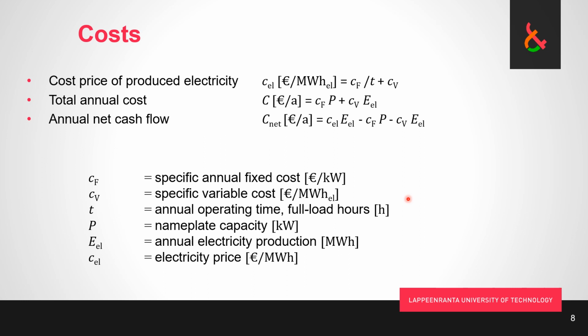So for example, in combined heat and power plants, typically they run a big part of the year at partial load. So we talk about full load hours. So that means how many hours the plant would have to run at full load to produce in a year the amount that it produces. So in reality, a typical cogeneration plant producing district heat, for example, might run for 6,000 or 7,000 hours per year, and 2/3 of it may be at partial load, so that the full load hours is going to be maybe 5,000 hours or something like that.